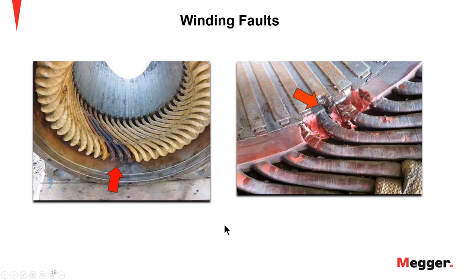So this one, I just want to show a little bit about what these faults look like. This image shows what a single phase fault would be. This is a fault in the winding of the stator, and you can see the discoloration of the insulation in the leads here. So it very well could have gone phase to ground in the system, or one of the phases had dropped loose. This could be one phase. We just don't know from looking at this example here.